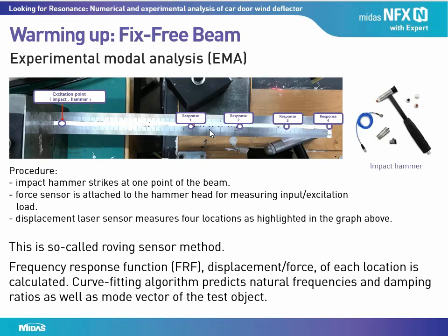For each strike, we record time history of input excitation and displacement waveform. Collected data are preprocessed to obtain frequency domain frequency response functions. The FRFs are then processed by a curve fitting algorithm to predict natural frequencies and damping ratios. Mode shapes are derived from the data as well.